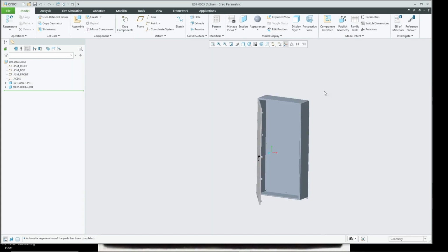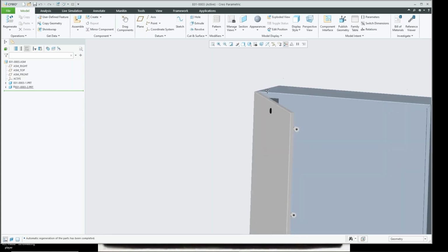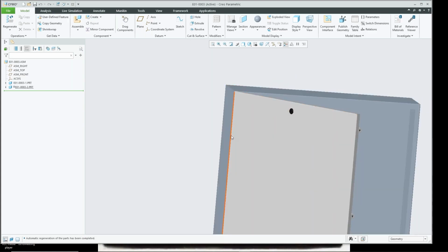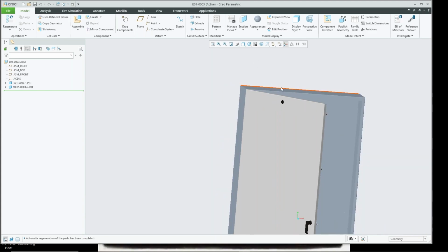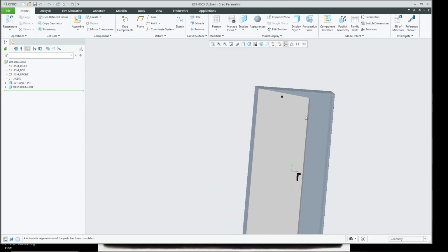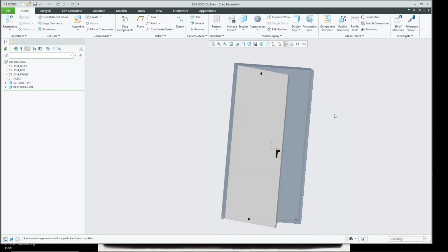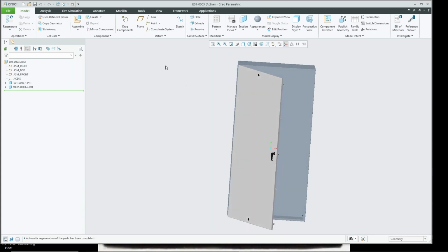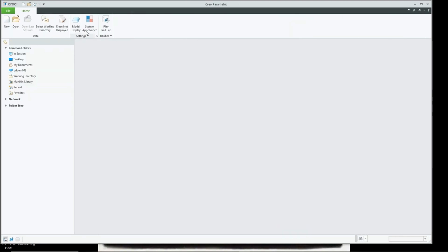All right, so that is a pin connection. So I showed you a few other functionalities inside of it, but once again, a pin connection is lining things up cylindrically, whether you're using the actual axes or cylindrical surface, and you're going to lock it down so it doesn't translate along that axis. It just rotates. And then once again, additional constraints to limit the actual angle that is opening or closing it. All right, so that is the first one.